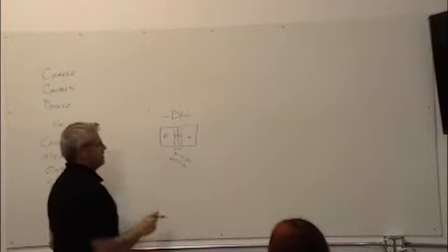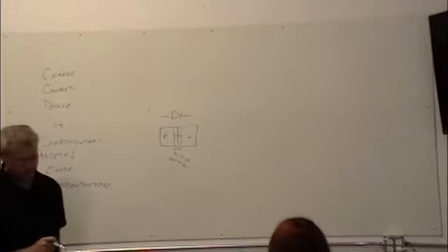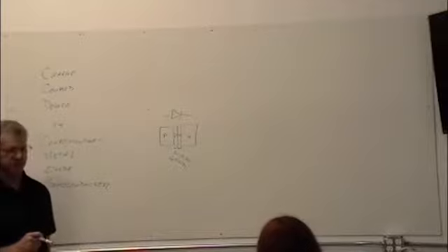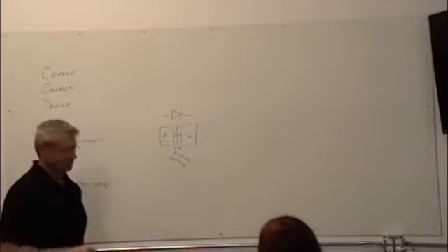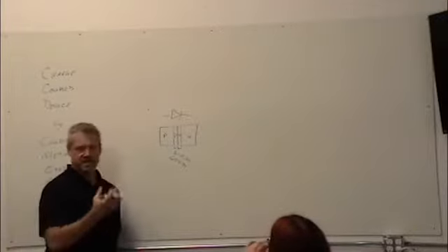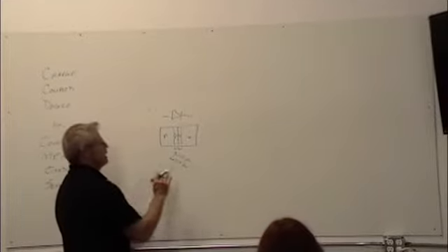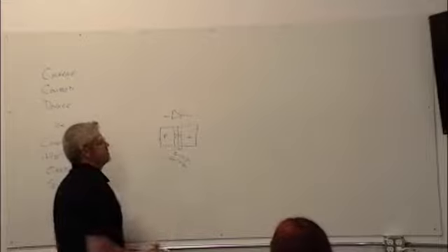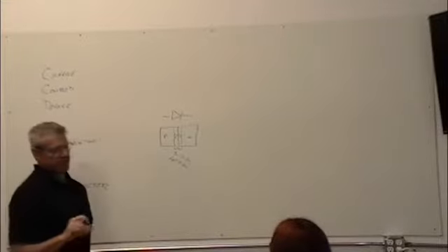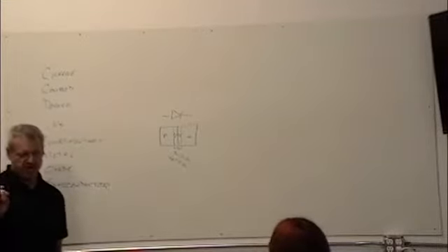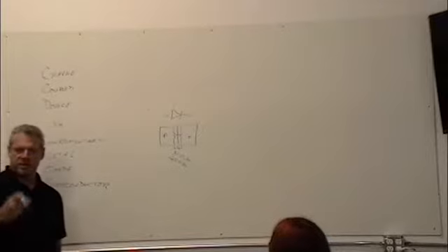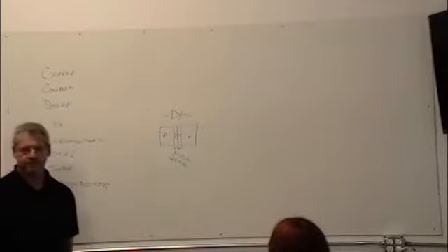And for silicon, I think it's between 1.2 and 2 point something giga electron volts, which is just a way of stating energy. And if you can put that energy into this piece of silicon, there is a chance that you can excite an electron to pop up into the conduction band and create an electron hole pair.